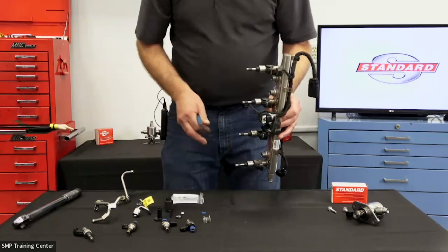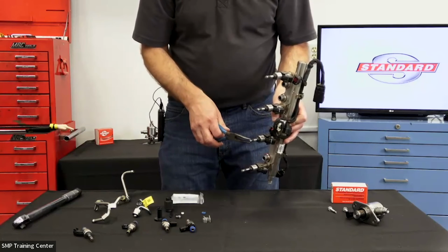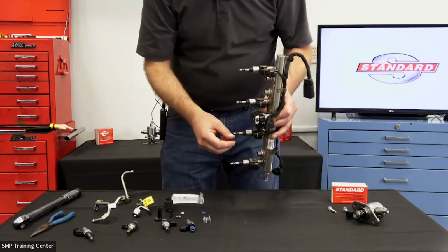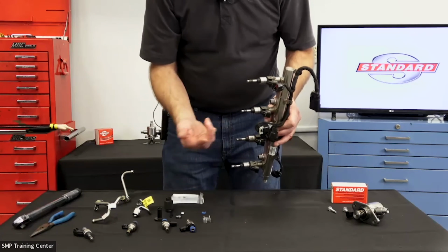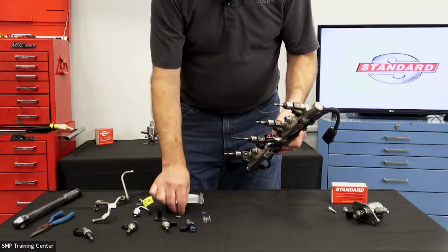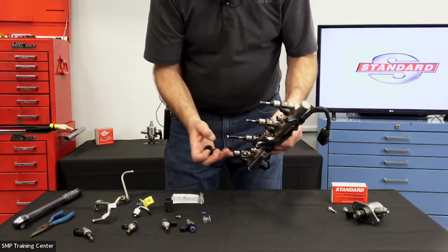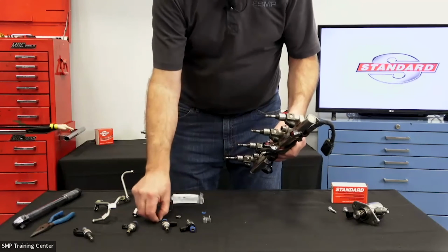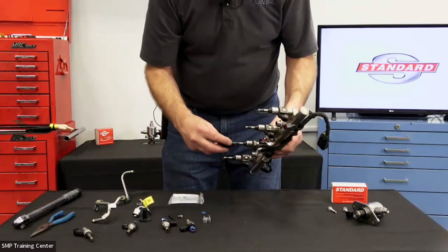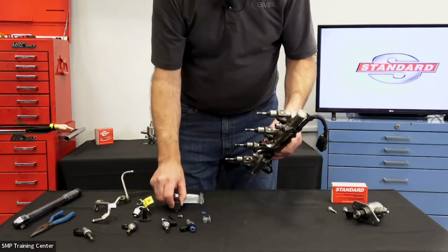So in order to replace those seals, to take the old one off, we can just use a pair of needle nose pliers. I'm not going to actually do it, but you would pinch that seal, and it would clearly break, or easily break, that Teflon seal off of there. And then to replace the seals, we have some special tools. There's a special conical shaped guide that we would put in place, then the Teflon seal, and there's a special pusher tool that we would push that up onto its land in order to install it there where it needs to be on the land. Once we do that, then there's a special sizer tool that we would use in accordance with service information. We would size the seal. Service information will tell you exactly how to do that.